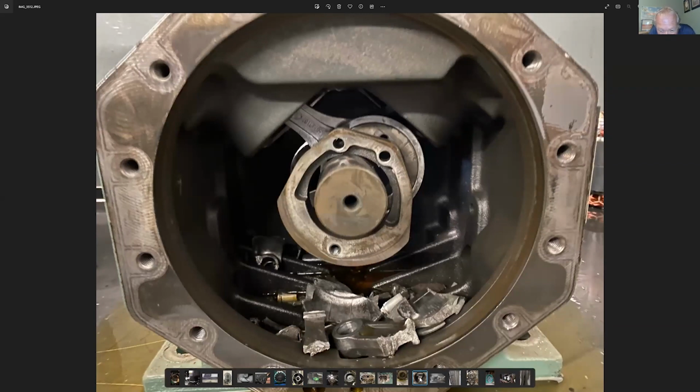Wow, that's a pretty neat picture there. Where did you get that one at? Well, it's out of a biscuit compressor, but it's the same thing. You need to look inside the compressor. Is it loss of oil or is it slugging that caused it? What happens to those rods? It's on journals, it's on a crankshaft, and if you got no oil, what happens to it? Seizes up. And then when it goes to start, you can snap the rods. Or it could be that flooded start that caused a slug to damage it.